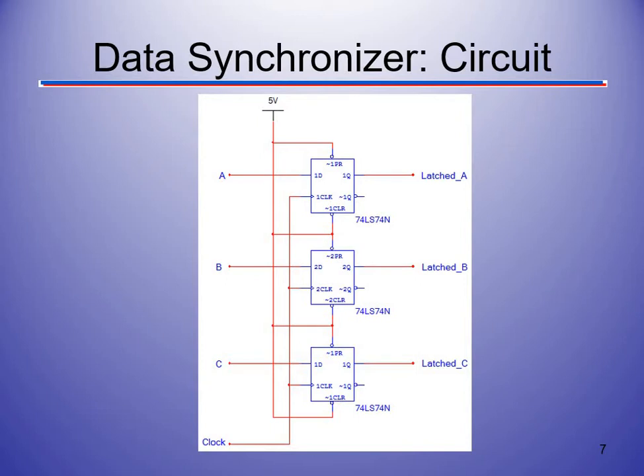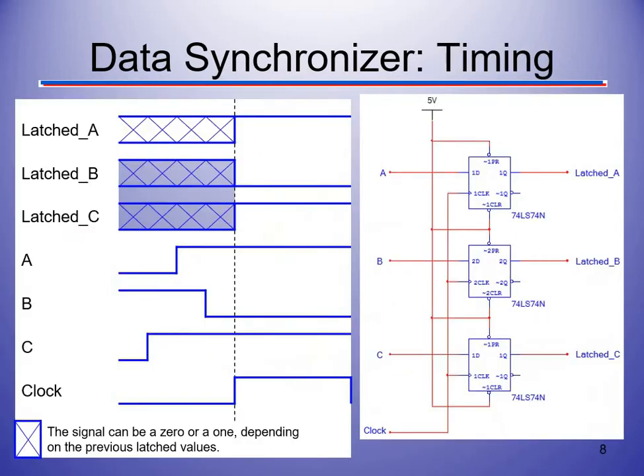You're going to synchronize the data at the same time. So when the clock signal rises, it's going to rise for all 3 flip-flops at the exact same time. So you're synchronizing the data. That's really the difference. The flip-flop's still holding the memory, but when they're all tied to the same clock signal, everybody's going to change at the same time.